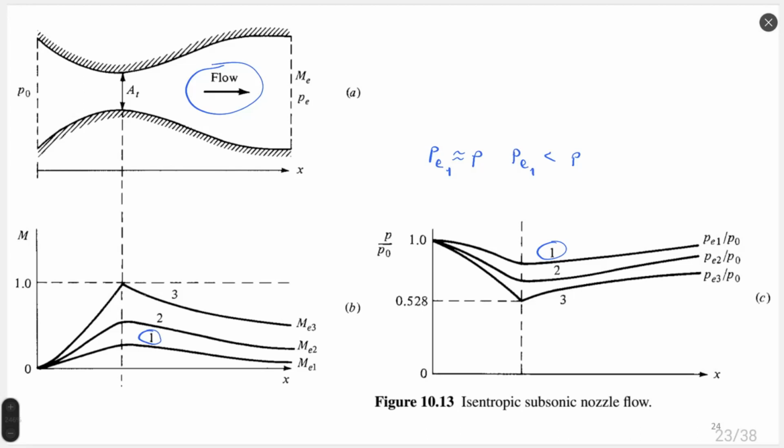You see that the Mach number increases in the first part of the nozzle. But since the energy potential of this flow is small, there is not enough energy to accelerate even to sonic flow in the throat; it's subsonic. Unfortunately, in the divergent part of the nozzle, the flow decelerates again because it remains subsonic.